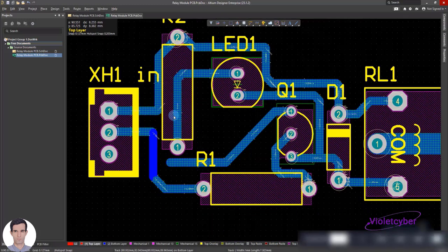If your circuit has such a path that only one jumper may be needed, it is recommended that you do not cut the circuit, and there is no need to use vias anymore. Now, we will talk in detail about vias in the next session, or change the paths again. Since I'm teaching, my goal is to design a circuit in principle. You can place the paths in such a way that these connections don't happen, and there's no need for vias, because if you put vias, it means you have to cut the circuit. And so it's more expensive to produce, and we want to keep the single-layer circuit.